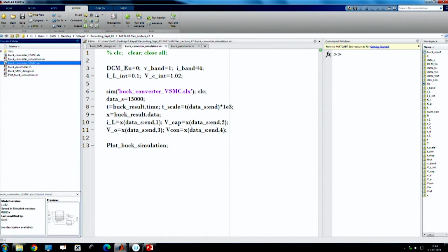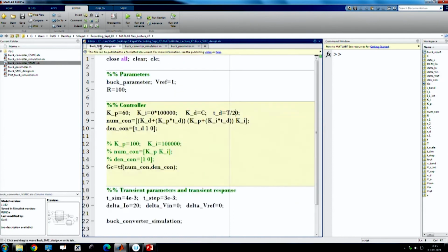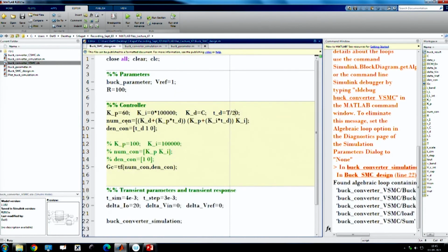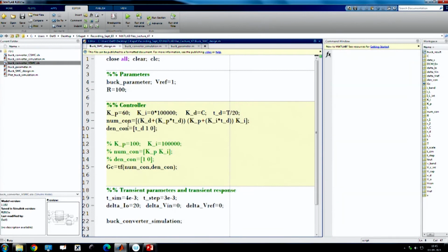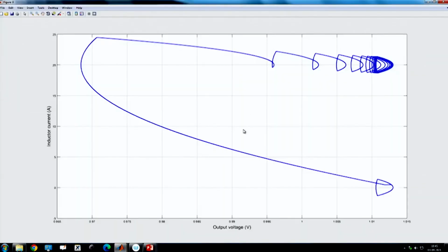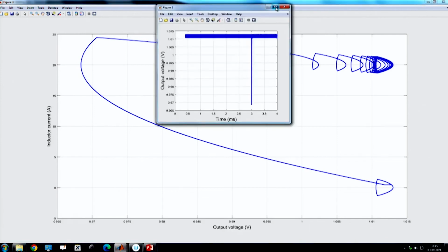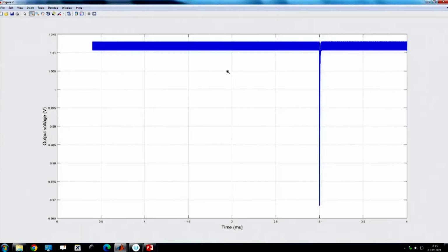Okay. So, the voltage band I have set 1 hysteresis, to achieve the desired value. So, let us see what happened. So, this is my voltage based realization, there is no current realization here, but you can see it is taking more number of cycles to reach steady state. That means it is not optimized, or it is not the optimal performance. So, you need to increase, but there is also steady state error.